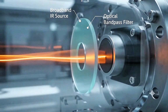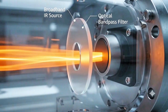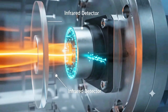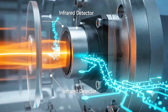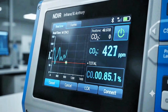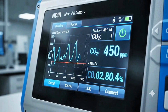Before we open it up and troubleshoot it, let's understand what's actually happening inside. The whole idea behind NDIR is simple. Every gas absorbs infrared light at its own specific wavelength, like a fingerprint. CO2 absorbs at one wavelength, CO at another, SO2 at another. If we shine infrared light through a gas sample and measure how much of that specific wavelength gets absorbed, we know how much of that gas is present.